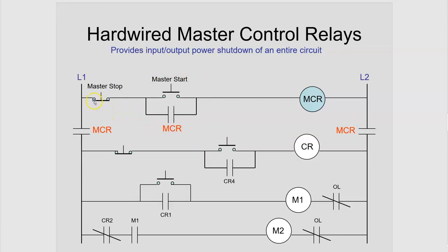Just to review, you have a normally closed push button. You have a normally open push button. When that push button that's normally open is closed, you have logic continuity through master stop. You have logic continuity through master start. And because these are in series, you have an AND, so this output then, the MCR, is true. Since this output and that parallel contact, which is ORed with the master start, normally open push button, since this is true, that causes this to go true.